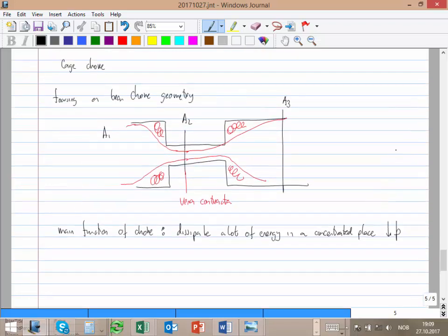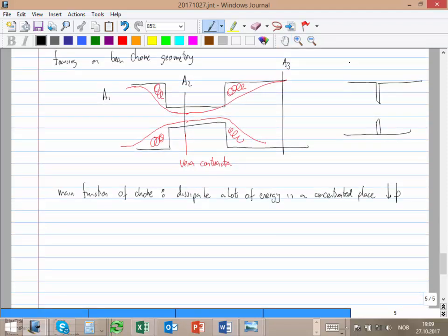Remember the other arrangement we use for metering, something like this, an orifice. The idea is that you drop the pressure locally, but then it has to recover. Here we make that very, very long, such that the recovery is very low. You don't recover much through the choke after that. That's the intention here. In the metering orifice you almost recover 100%, because you don't want to drop pressure.